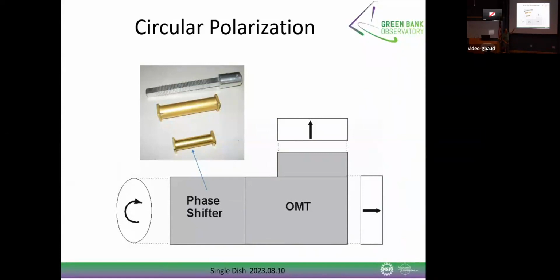It's fixed to be circularly polarized. In some of the lower frequency receivers, there's a switch in there. You can switch in a hybrid. I think S band has C band down. There's an external switch that allows you to convert linear to circular. Everything above that has this OMT. Some of them don't have a phase shifter and are linear polarized. Some of them do.